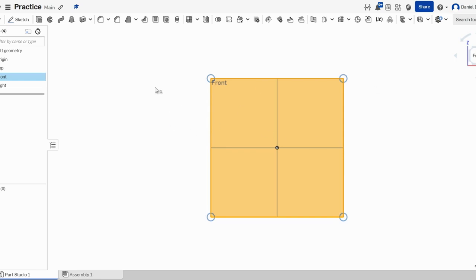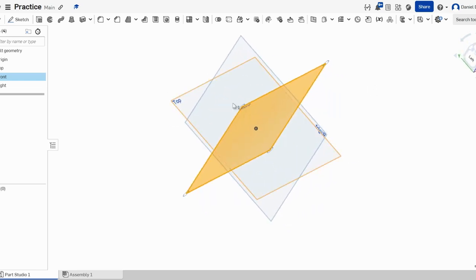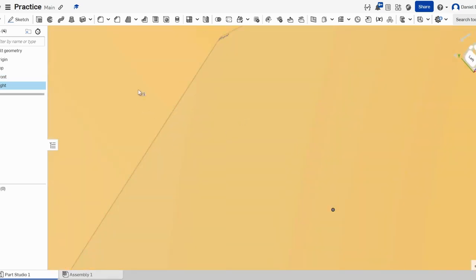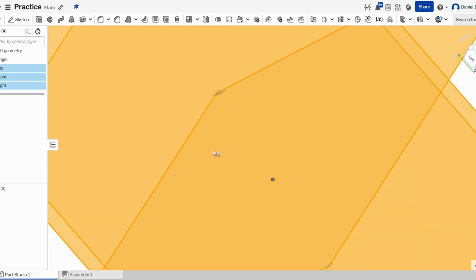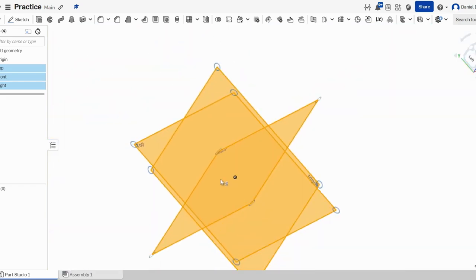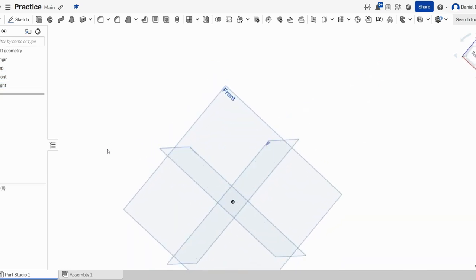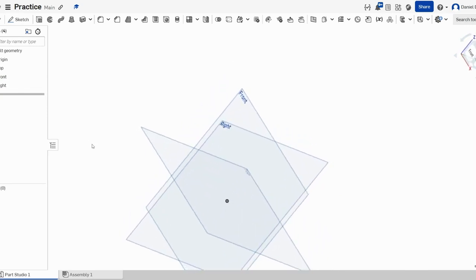One other one that you might use a lot as you're clicking on things: you might select multiple objects like this, and if you're zoomed in, it's hard to deselect because you can't see what you're doing. So to deselect everything that you have selected, press the space bar. That's what I just did. Space bar will deselect all things that you have selected, and that's really handy.